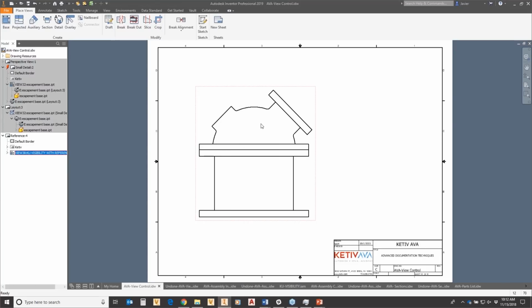In this case here, I'm going to go ahead and find it in my browser, or maybe right-click and just make it transparent here, right? So it's a little bit different. It doesn't show it as hidden lines. It shows it as if this were made out of glass. Okay, so just another way to view things, and if you're trying to communicate what's inside of that component, this is one way to do it.